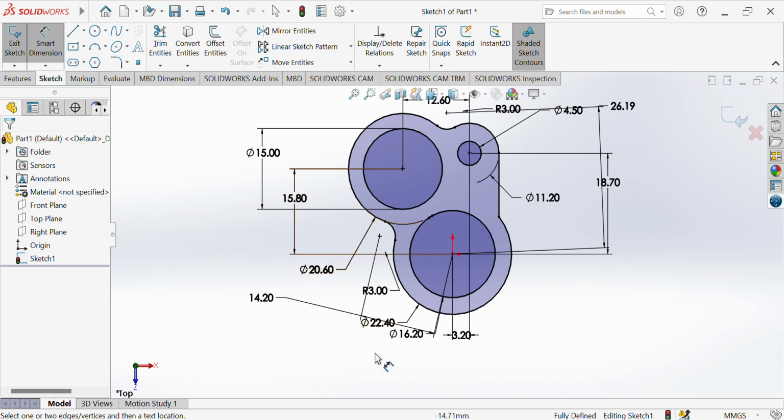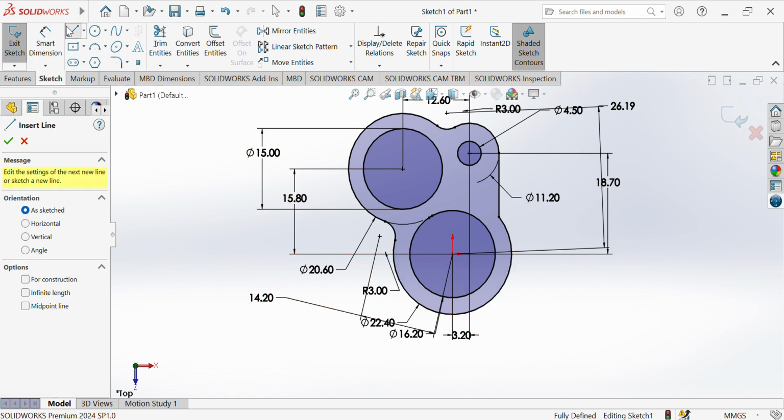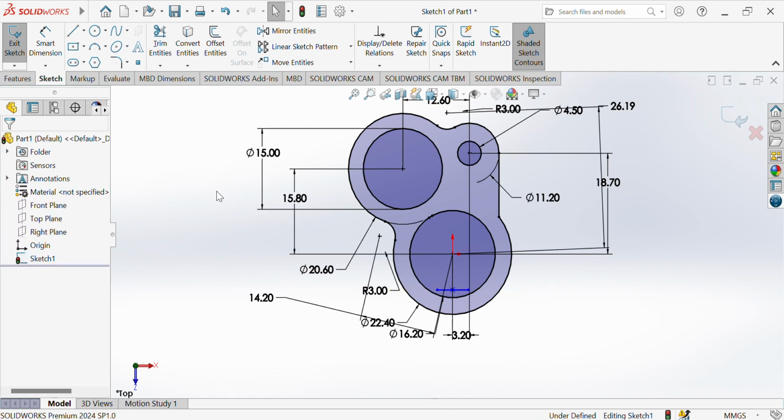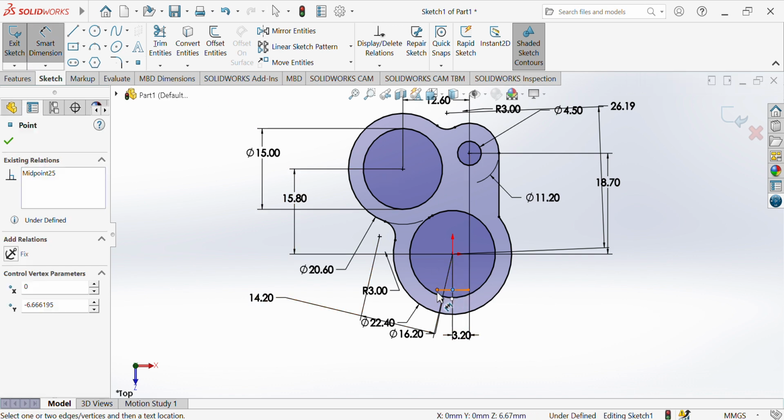But now there's something I almost forgot. This particular part has a breakage here. So let's just use our midpoint line. So just following this center of the drawing, just draw a line. The line has a full length of 5. Escape. So you just small dimension from the center to this point to be 2.5.